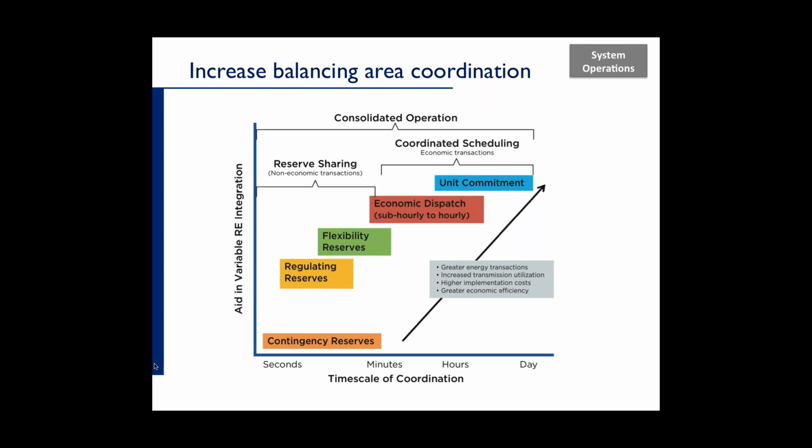It's a very common thing. I know in the United States we've been doing this for decades, and it does help a little bit with renewable integration, but not so much, because most wind and solar is never going to be large enough, and the output will never change fast enough to constitute what we call a contingency, which is a sudden drop in output that happens in sub-seconds.